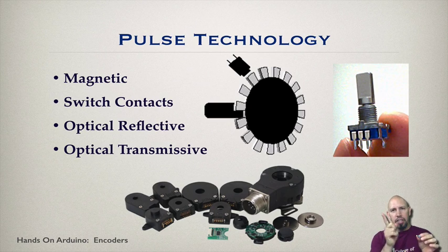Basically there are a set of switches that are connected here. And depending on where the switches are positioned, you will get a connection. Notice that this connection has 3 connectors associated with it. One is for ground, and then the other 2 are for phase A and phase B. When you use something like this, it has to also be connected up to power somewhere. The power is going to somehow come through these, and you probably need pull-up resistors and stuff like that. So there's additional circuitry required to be able to use them.